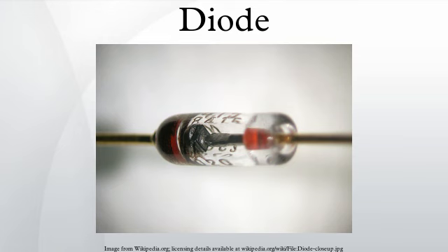They also enable tunable oscillators in early discrete tuning of radios, where a cheap and stable, but fixed frequency, crystal oscillator provided the reference frequency for a voltage-controlled oscillator. Zener diodes. These can be made to conduct in reverse bias, and are correctly termed reverse breakdown diodes. This effect, called Zener breakdown, occurs at a precisely defined voltage, allowing the diode to be used as a precision